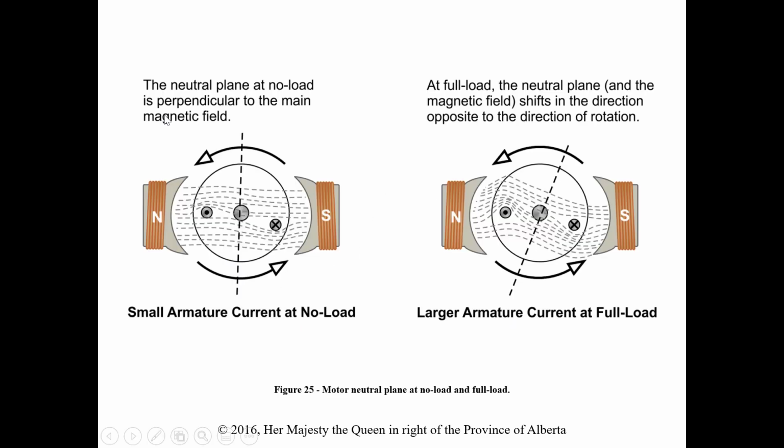Still have the same effects. Again, at no load, we have our neutral plane. Again, think that we're still sending source voltage, or applied voltage, through these brushes and windings. So we want to do it at a point where they're not going to be generating a ton of CEMF, because we will get arcing and such at that position again.